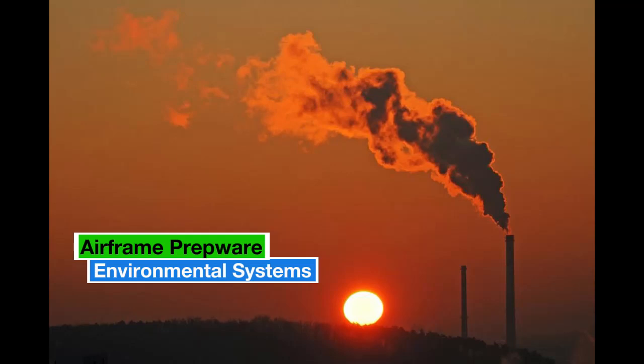An aircraft pressurization cycle is normally considered to be one complete series of events or operations that recur regularly. When purging a Freon air conditioning system, it is important to release the charge at a slow rate. What is the reason for the slow rate discharge? Prevent excessive loss of refrigerant oil.